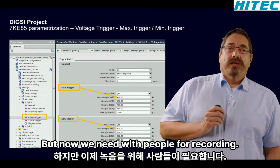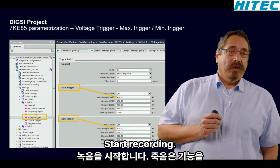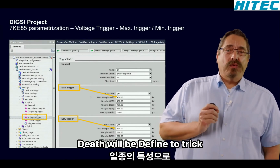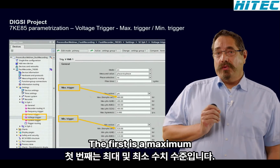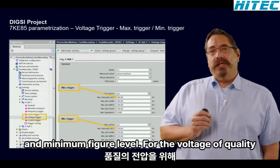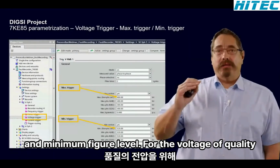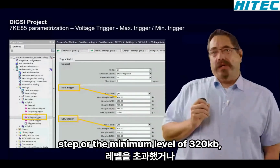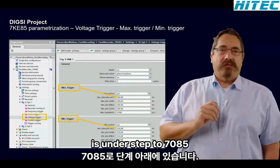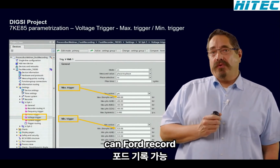But now we need to equip our fault recorder to start recording. Therefore, we define two trigger functions for two kinds of characteristics. The first is a maximum and a minimum trigger level for the voltage. Either when the max limit of 480 kV is overstepped or the minimum level of 320 kV is understepped, the 7KE85 starts to record a so-called fast scan fault record.